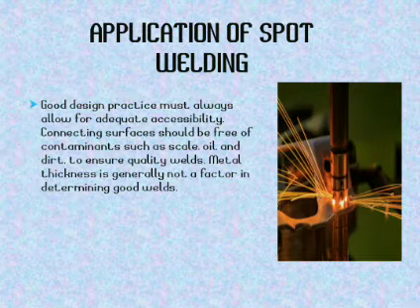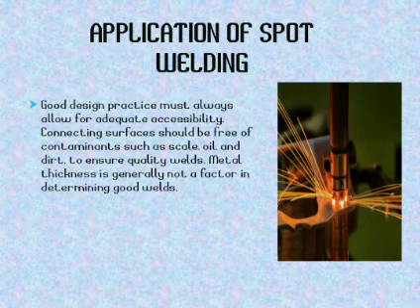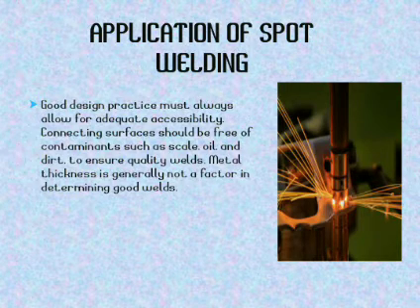It also has a good design practice: it must always allow for adequate accessibility, and connecting surfaces should be free of contaminants such as scale, oil, and dirt to ensure quality welds. Metal thickness is generally not a factor in determining good welds.